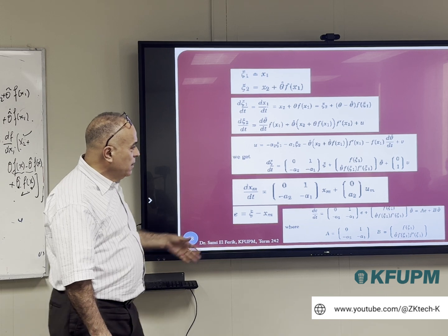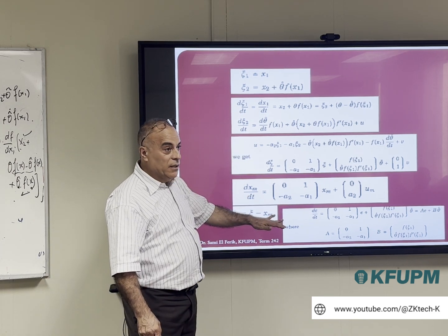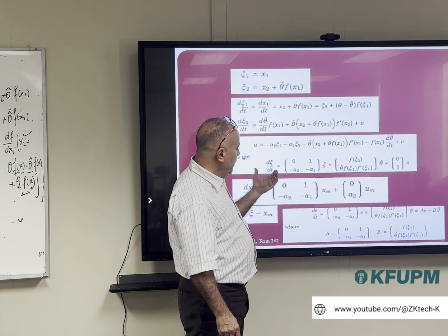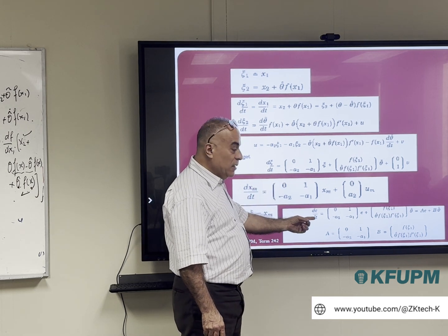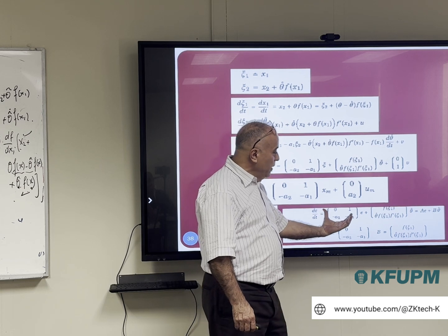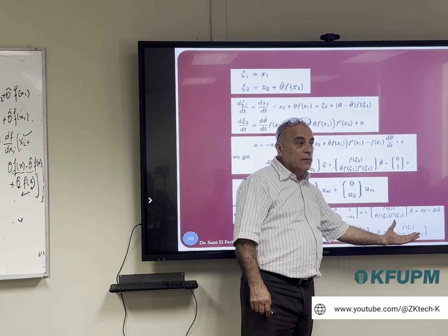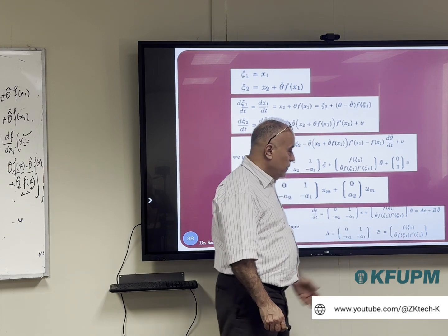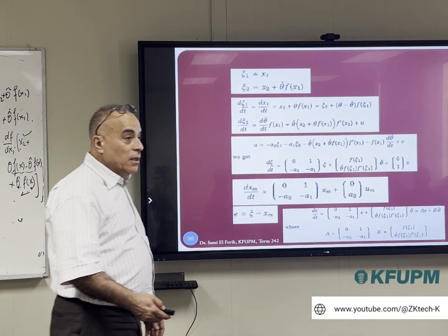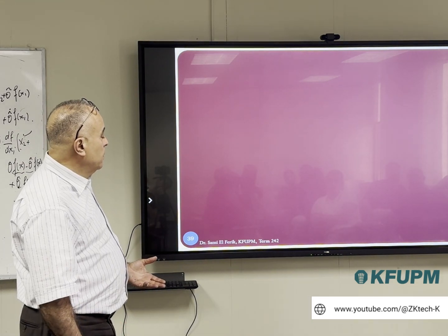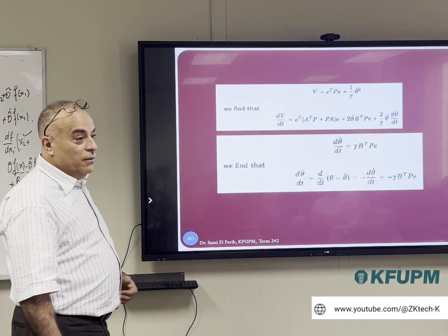How to deal with this? Everything else is mathematical representation and how to manipulate this. But normally you are going to have a dynamic of error, where you have the desired dynamic plus a term that you would like to take off, to make it equal to 0. In order to make this term equal to 0 and guarantee the stability, we use our friend Lyapunov.